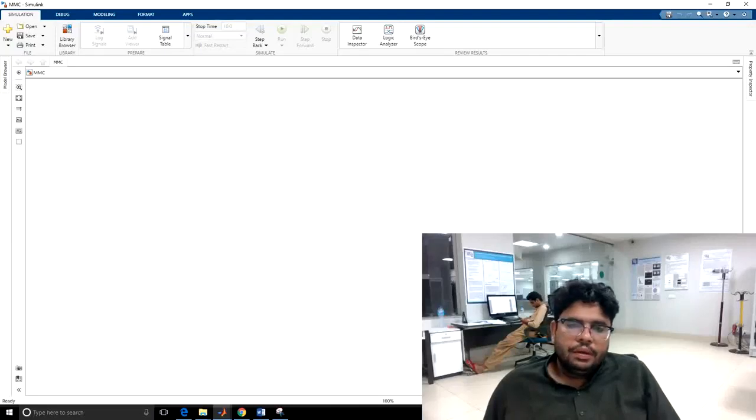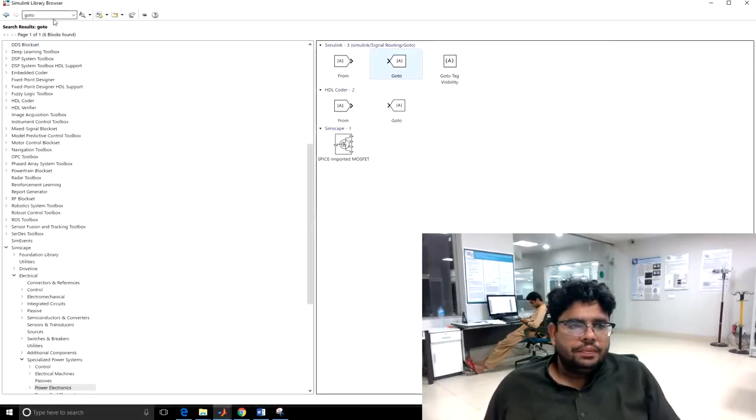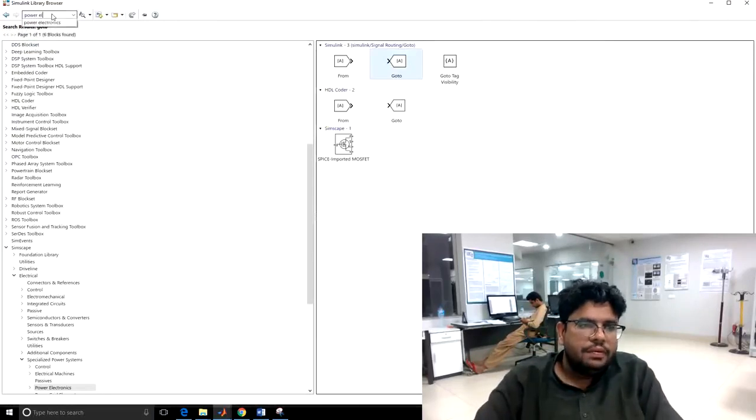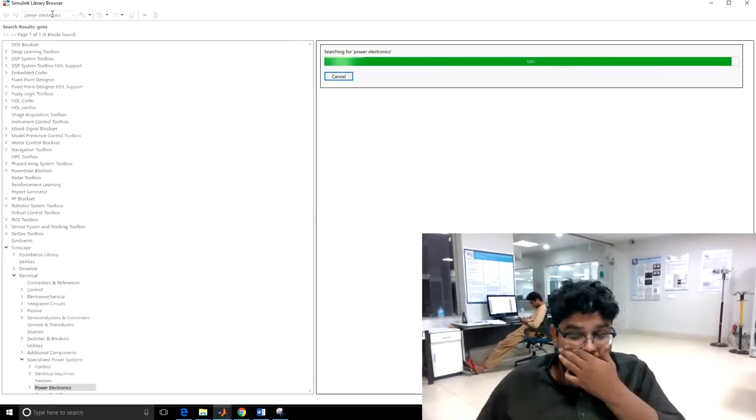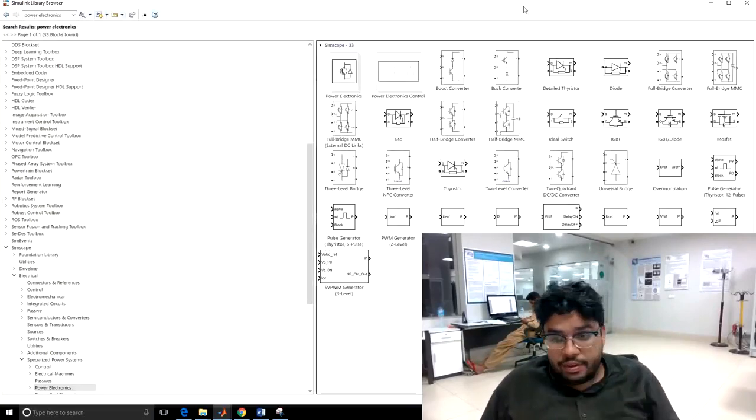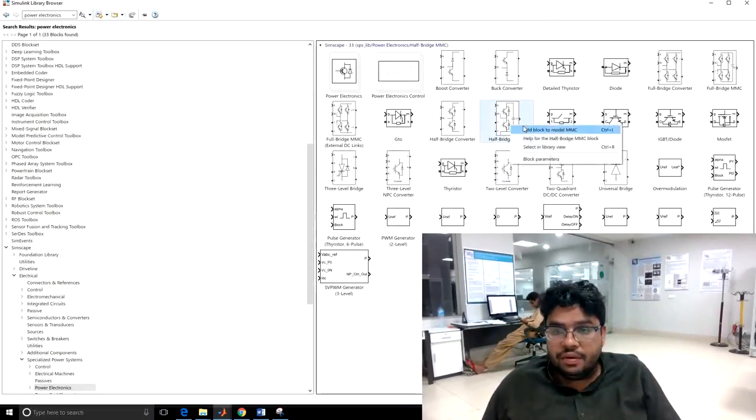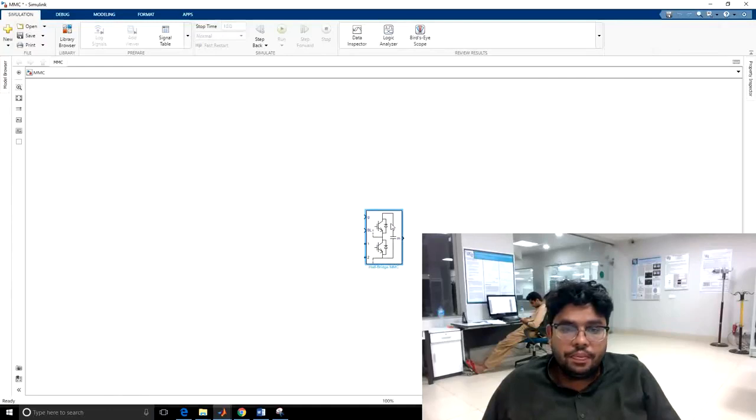Bismillahirrahmanirrahim. In this video we will discuss how to design a modular multi-level converter using nearest level control modulation. We will design an 11 level single phase MMC at first. So for this we go to the library browser and we go to the power electronics. We are designing this MMC by using half bridge MMC, therefore we pick up this half bridge MMC.